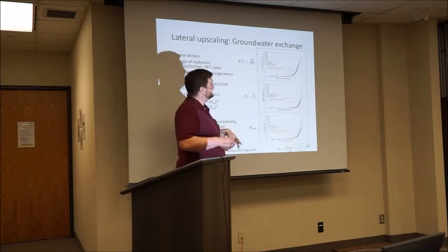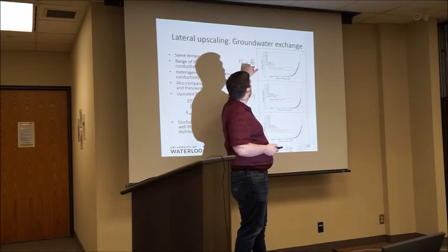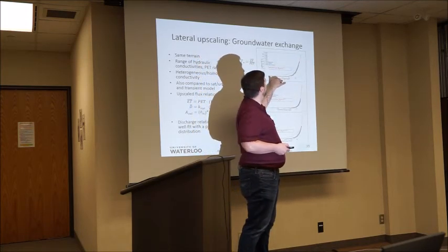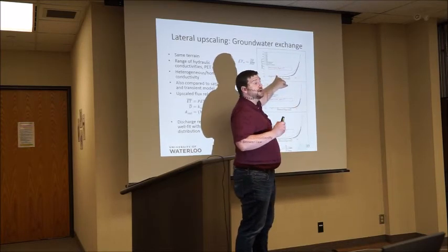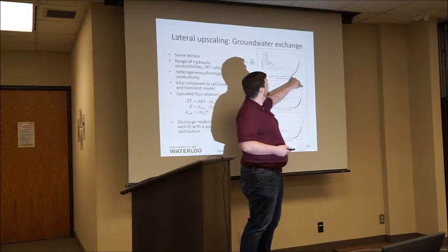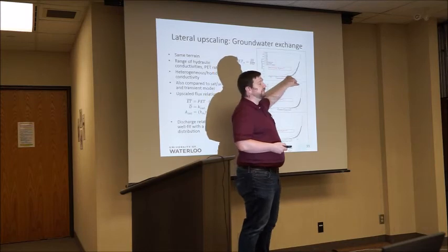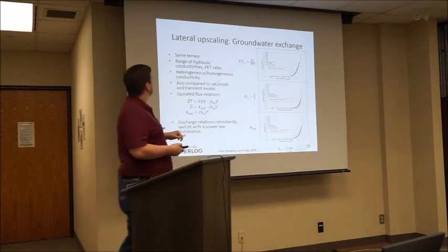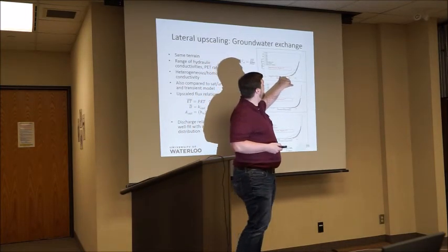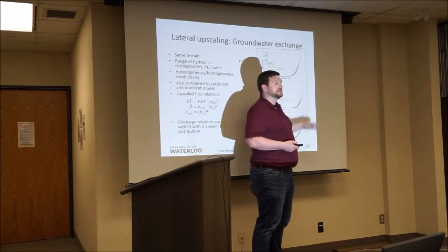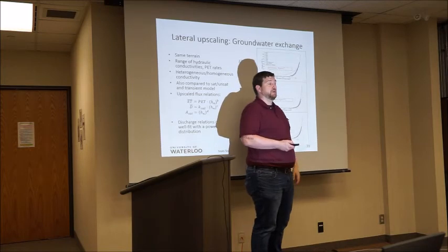added recharge, steady state conditions, determined the head, and we got these relationships between ET and normalized head under a variety of conditions. So this is under a number of different hydraulic conductivities. Again, initially homogeneous. This also includes heterogeneous hydraulic conductivity. What was the other thing that was modified here? I forgot. Various PET rates, and they were unnormalized PET rates, and they all collapsed along this same curve. This is that natural simplification of the system that's leading to a power law relationship.